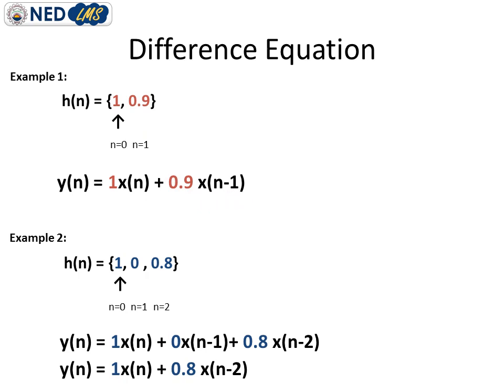Here you can see n is equal to positive 1, positive 2, positive 3, and in writing the difference equation, we provide the delay equal to the amount of shift. The positive shift is transformed to negative, and the same coefficient is attached to this delay.